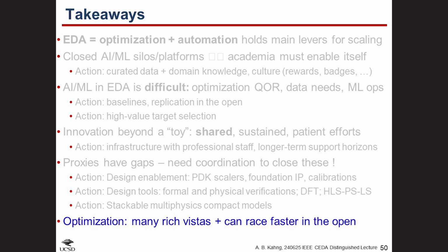And this slide shows place and route tool noise for the AES design, same enablement. The 5 input netlists in this picture are synthesized with target clock periods ranging from 278 to 282 picoseconds, stepping by 1 picosecond per netlist. And then to study noise in place and route, we set the target clock period to 280 picoseconds. And then there's 5 times 201, so there's 1,005 PNR results in each of these plots. And we observe a variation of 15% in effective clock period across these 1,005 results.